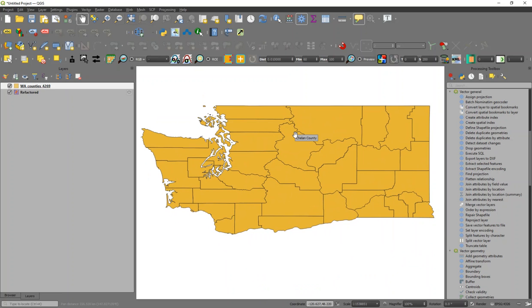And the last thing I want to show you, since I'm 3 times longer than I thought I was going to be, is what is called the status bar down here on the bottom. And in the status bar, there's a couple things you should notice. There's your coordinates right here. So as you pan around your map, your coordinates will change. They're specific to where you are. Notice that my coordinates are in latitude, longitude. And I can confirm that because I am in WGS 84, which is a geographic coordinate system, and they are always in degrees, or units of degrees.